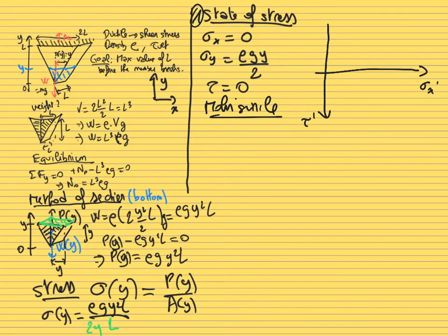As a reminder, the y-axis gives you the value of the shear stress. Once you have this, the first thing is we need to find the position of the center of this Mohr circle. The center is given at the average normal stress along the x-axis and at 0 along the y-axis. The center is always centered around tau equals 0.